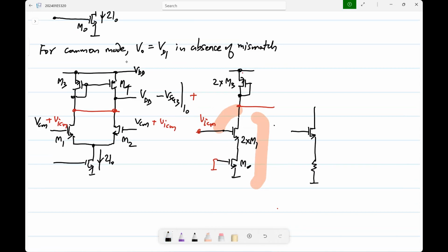What is this alone? This is a particular type of current source. What is it? This is a voltage controlled current source. If the GM is very large, there is feedback, right? If the GM is very large, what happens to the incremental VGS? It will be 0. This is in feedback. There is negative feedback in this. This I think you have seen in the previous course. So if the GM is very large, incremental VGS is 0.